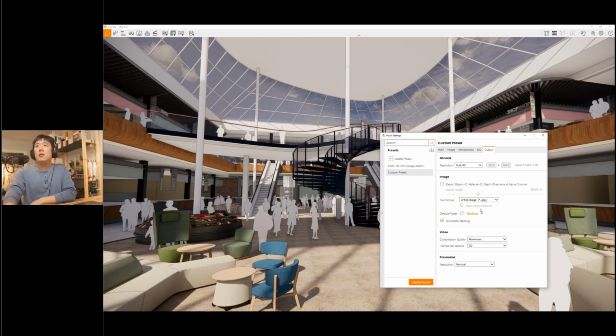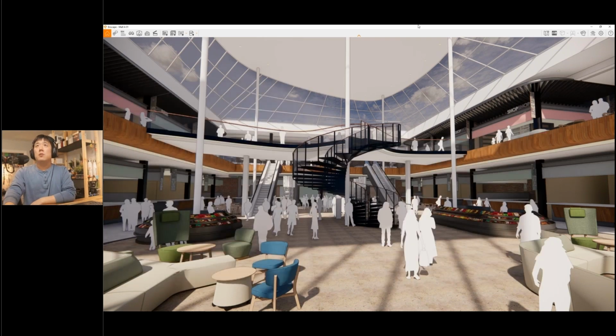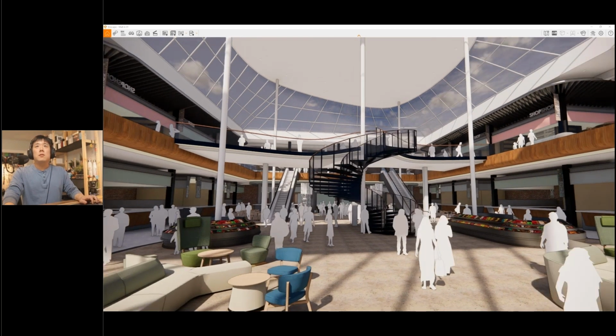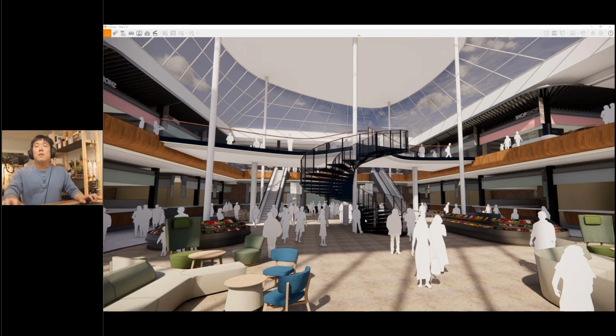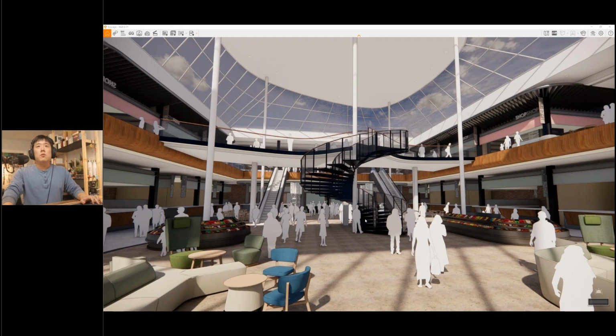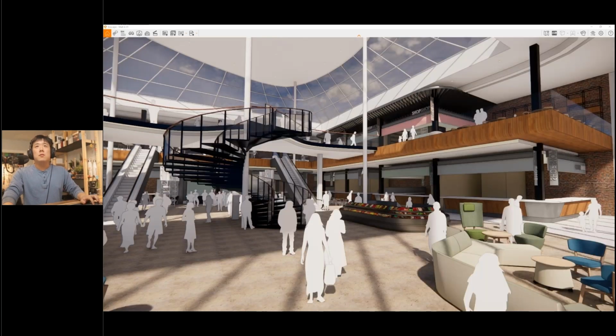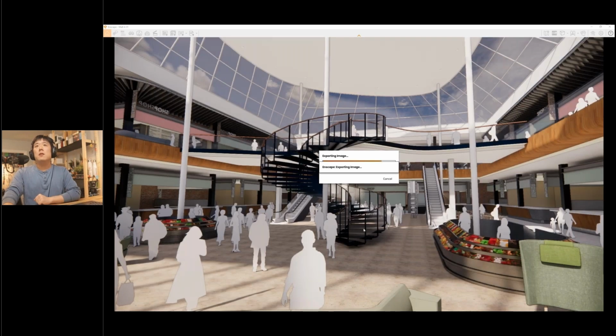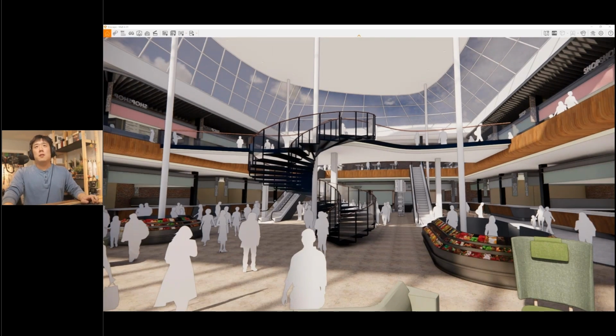Then I use the shortcut Shift F11, which is stated here on top of the screen. Once I arrive at a spot where I want to talk about the scene, I press Shift F11 and it renders away for me. Then I move away a little, look at it from a different angle, press Shift F11 again, so I can do that in quick succession.